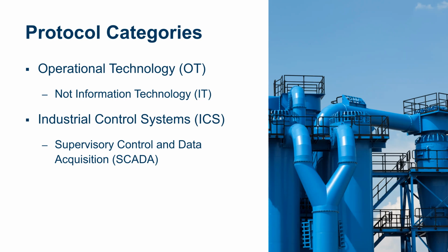But what if you have several different, let's say, assembly lines in a factory, or several factories, or a bunch of refineries, or a whole bunch of substations in the power grid, right? Now you have a whole bunch of different industrial control systems, and you might need visibility into those systems. And that's where SCADA comes in. You have supervisory control and data acquisition, where you have a concept of hierarchy. So you have some sort of human machine interface up at some top level. There's an engineer at a computer, and he has visibility into multiple processes. And that's typically the distinction that SCADA adds in, is you have not necessarily direct device-to-device control of a whole bunch of devices, but instead aggregated and carried up to some sort of human, so that they can make decisions on a process or multiple processes.